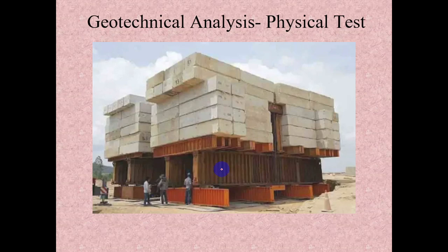Here, what could be the diameter of the pile and how much length of the pile has to be embedded into the ground, all those things come under geotechnical analysis. After using the empirical equation, usually we analyze, but before execution, if suppose 100 piles are going to be installed here, at least one or two piles we need to test physically like this.